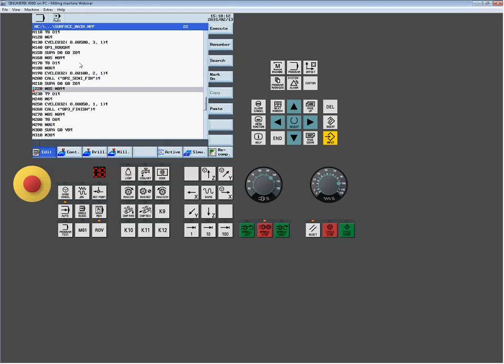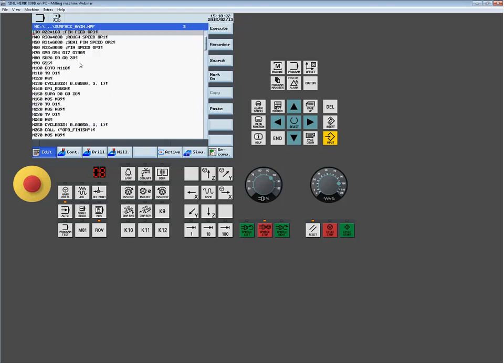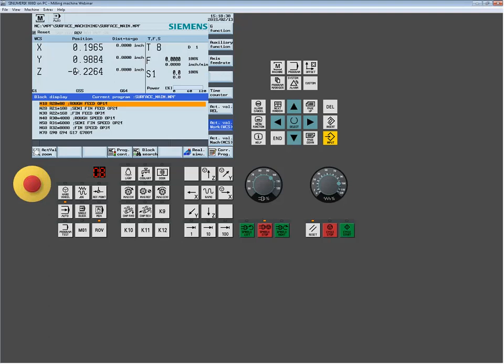And make sure the spindle's off, coolant's off. It's going to change tools to tool 9, whether it had it or it didn't. And then it's going to load up my cycles and start running. So if you just go to this go-to and change the go-to call to 210, I'm still running the program from the start. So we're going to hit it right from the start, but watch what happens.